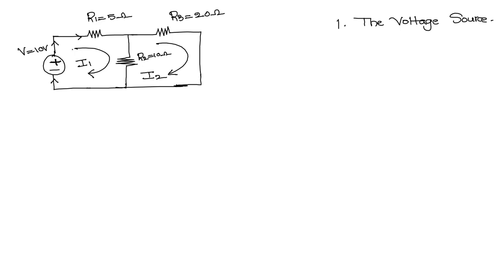That is the reason the currents flowing in loop number 1 and loop number 2 follow the direction based on the positive sign of this voltage source. Clear? So in this problem we have taken the direction depending upon the positive terminal of a voltage source. After that we are going to discuss many problems based on the mesh analysis concept, and I am going to solve more problems.